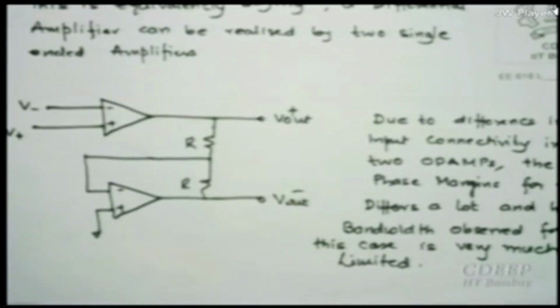What is that? Common mode feedback, CMFB, every time. Okay. Essentially what is the common mode voltage? Vout plus and Vout minus added and divided by 2, the average value of that. I want to hold it, but if Vout changes, then how do I hold it? That means subtracting something from one must be the same as adding to the other so that the average value remains constant. That is what common mode feedback does. It holds that value. Okay, and if it holds, then much of your problems are solved.